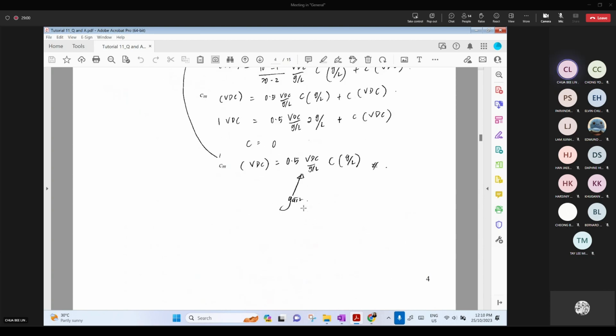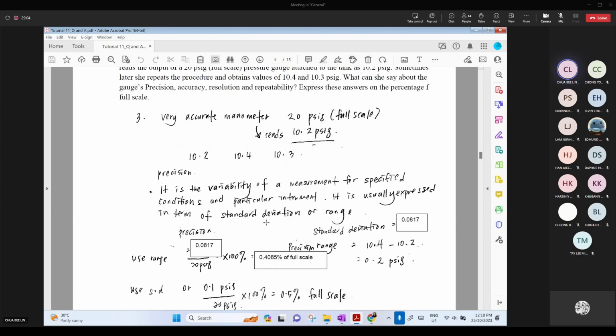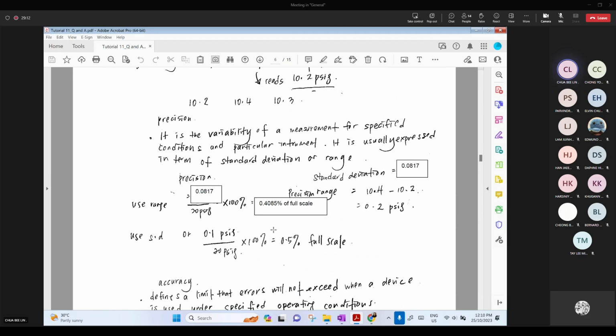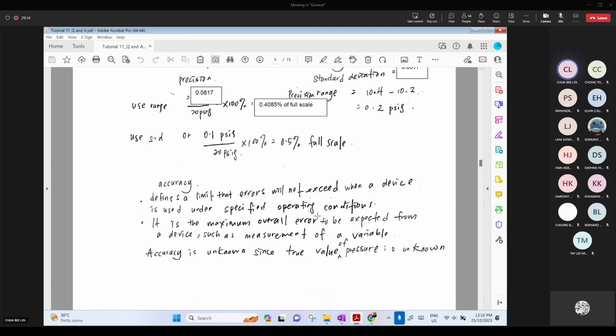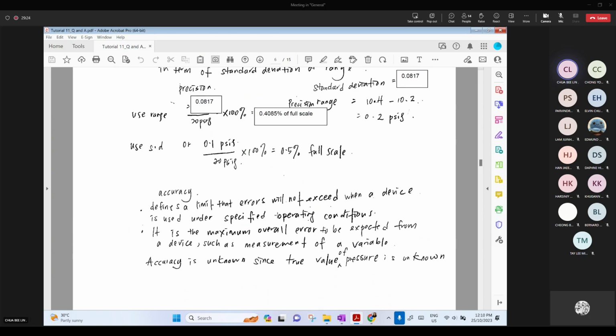Exactly, I think just a different transmitter and then a simple calculation to calculate accuracy. I prefer you to use the standard deviation instead of using the range value. So use this value. Please go through the simple calculation to calculate the accuracy, standard deviation, mean value, the average value, everything like that.